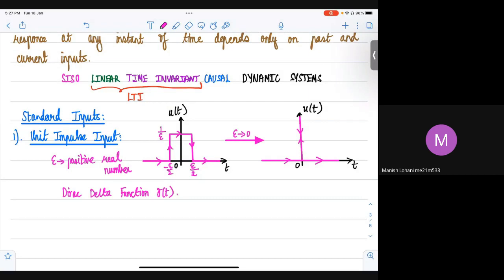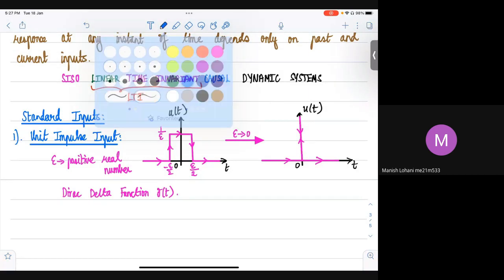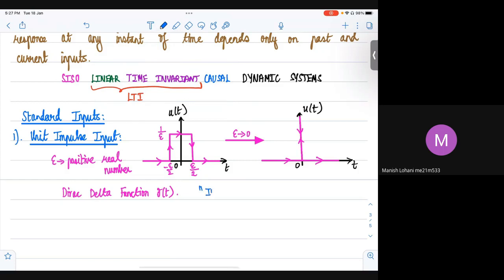When you provide the impulse input to a system, the corresponding output is what is called the impulse response of the system. So let us say we have a vehicle and we provide an impulse steer angle. Then whatever output we get is what is called the impulse response. In fact, in vehicle dynamics evaluation, there is a test called a pulse steer test, where the steering angle is given an input suddenly and then it is brought back to the center position. So the idea is essentially to generate as close to an impulse as possible.